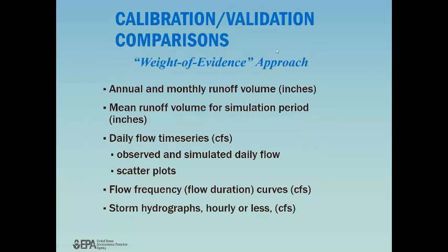This involves, for hydrology, looking at annual and monthly runoff volumes, the mean runoff during the simulation period, the daily time series of observed and simulated daily flows, scatter plot, the flow frequency curves. Typically it's done for daily values, and for storm hydrographs, hourly or less.